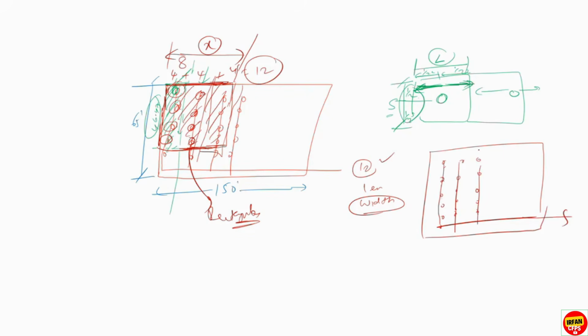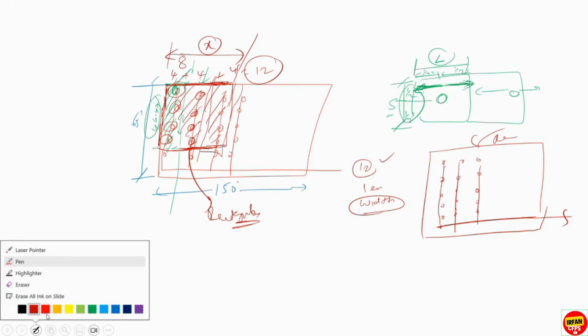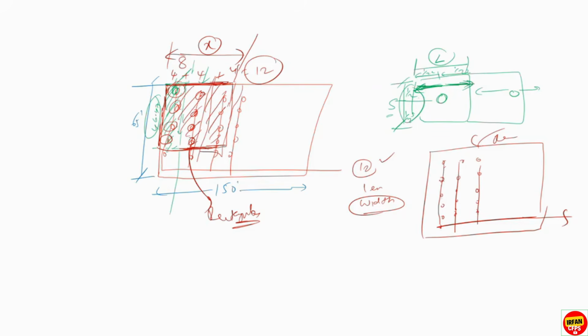This is the line. This is the row. So most of the designers, when you review the design, you have to check these points. That's why I'm explaining it to you. Most of the designers, when they design the area, they consider all the sprinklers in the loop or the branch. For example, here you have 5, irrespective of the length.